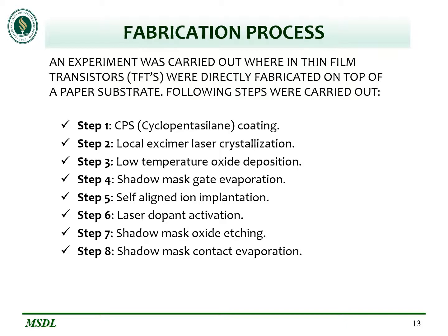There are 8 steps: cyclopentasilane coating, local excimer laser, low temperature oxide deposition, shadow mask gate evaporation, self-aligned ion implantation, laser dopant activation, shadow mask oxide etching, and the last step is the shadow mask contact evaporation.